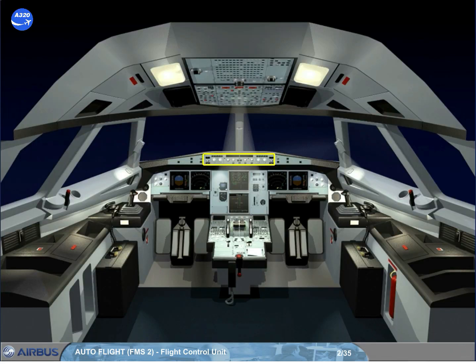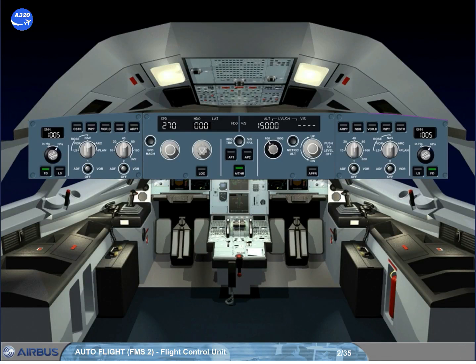The Flight Control Unit, or FCU, is the Short-Term Actions interface with the FMGS. It is used to arm or engage the guidance modes and to select their associated targets. It is also used to set the autopilots, APs, and/or autothrust, ATHR, on.